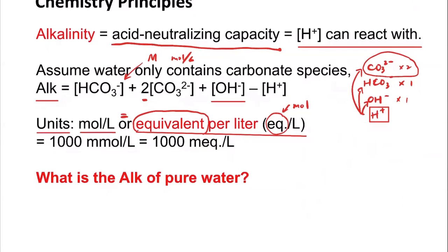And because the ion concentration in the water is normally quite low, people also use the unit of millimole per liter. That's just 1,000th of a mole, so 1 mole per liter is equal to 1,000 millimole per liter. And also for equivalent, people came up with this unit here, MEQ, milli equivalent per liter. So 1 equivalent per liter is equal to 1,000 milli equivalent per liter.